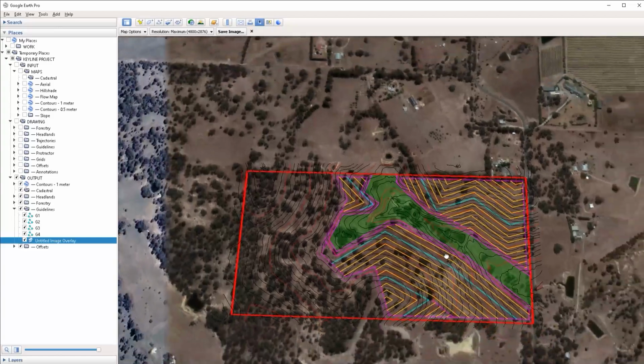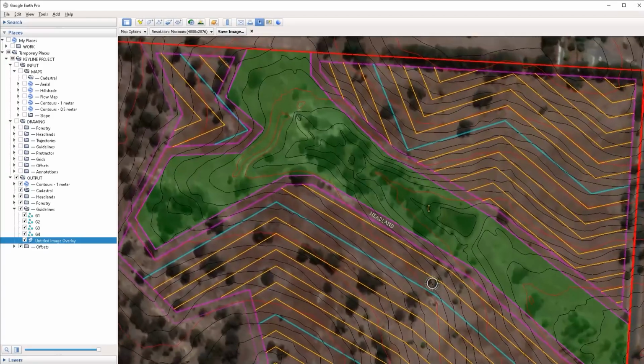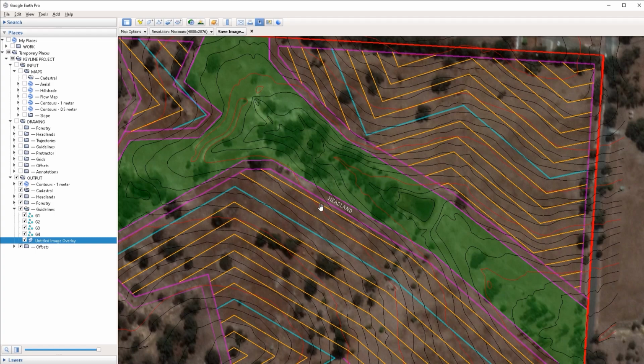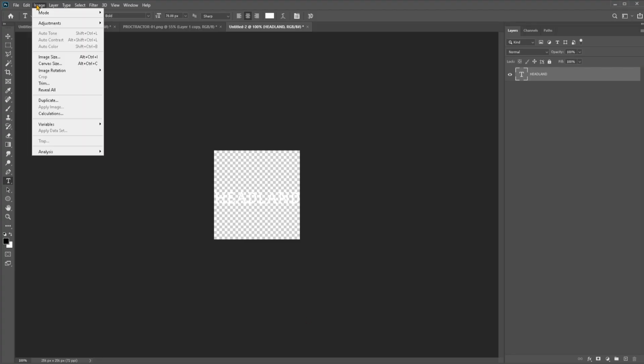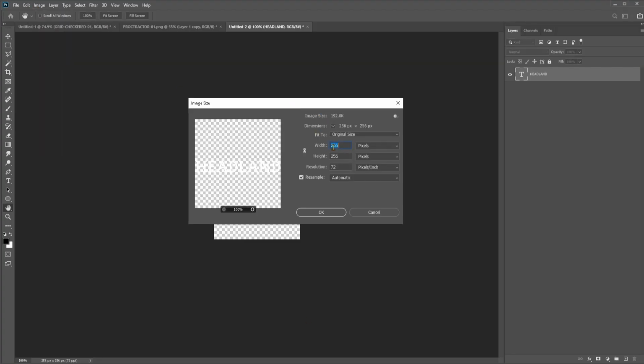And now this text is going to stay there, so whoever inspects the drawing can view it. Now you can add as many annotations like this as you want. One thing that I will say is that if you're preparing these kinds of overlays for annotations, just make sure that the image does not exceed more than 512 pixels wide, because if you have many annotations, then they may slow Google Earth down, because these are, after all, images that Google Earth has to load to display them.